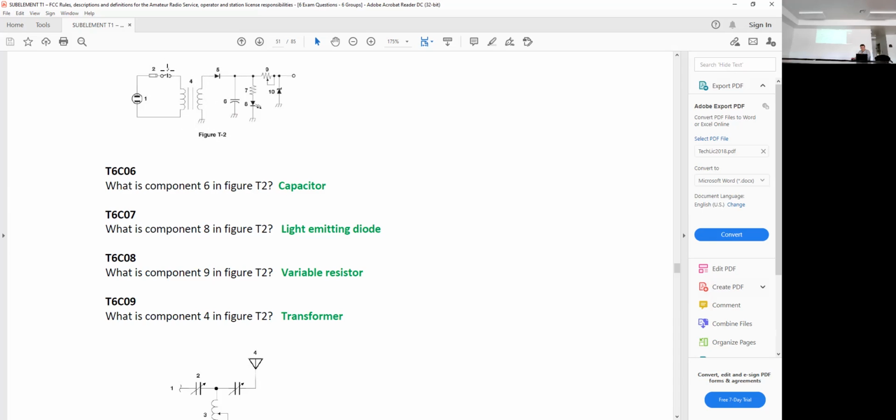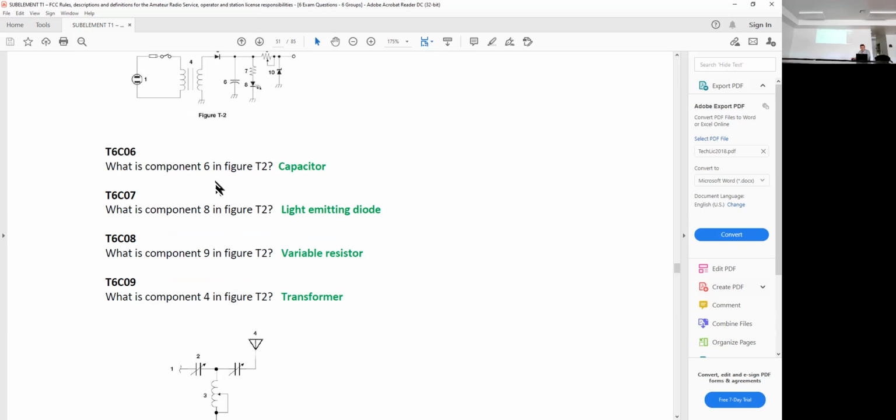And the difference between the two, if you tore it open, there'd be more turns of wire on one side than the other. And you can flip them around. If you take a step down transformer and you want to use it to shock your cows and keep them in their pen or whatever, you can just flip it around and hook her up. It'll turn that voltage real high.